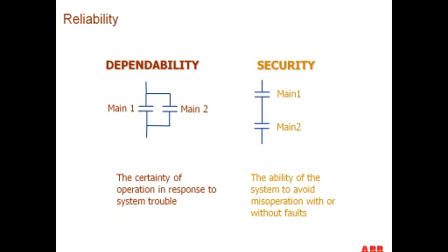Yes, a dead tank breaker is one that you usually see where the tank of the breaker is at ground potential, and the current transformers are typically located on the bushings going up to the line. For the live tank breaker, you'll see a long bushing column, and the head of the breaker where the interrupter is actually located is at line potential above the insulator. So that's the difference between the two of them. And the tank on the live tank breaker is at line potential, so you can't touch it when it's energized. Hope that answers okay.